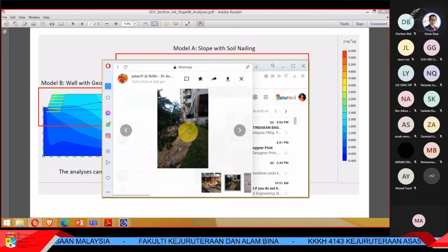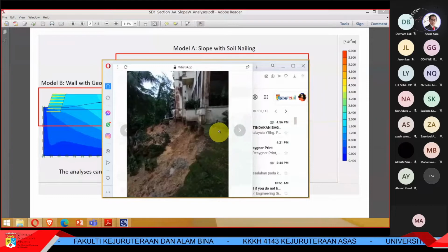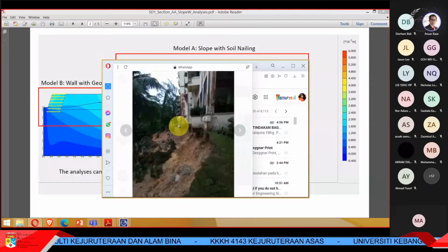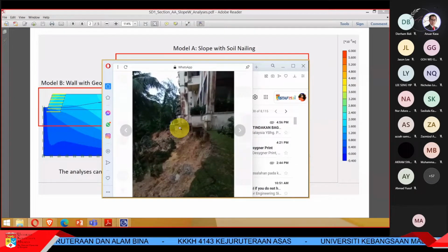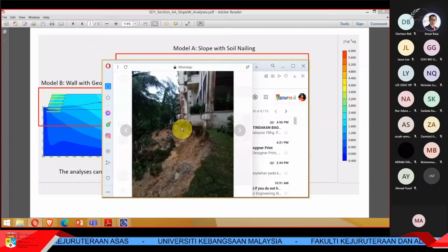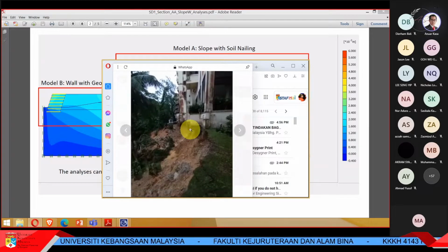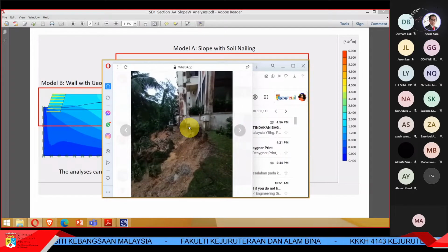If you look here, actually there is a pile here. Exactly here it is off, about 1 foot off, meaning that the pile is hanging. So the left side of this 7 story building, the foundation here is hanging, meaning that it becomes a cantilever.